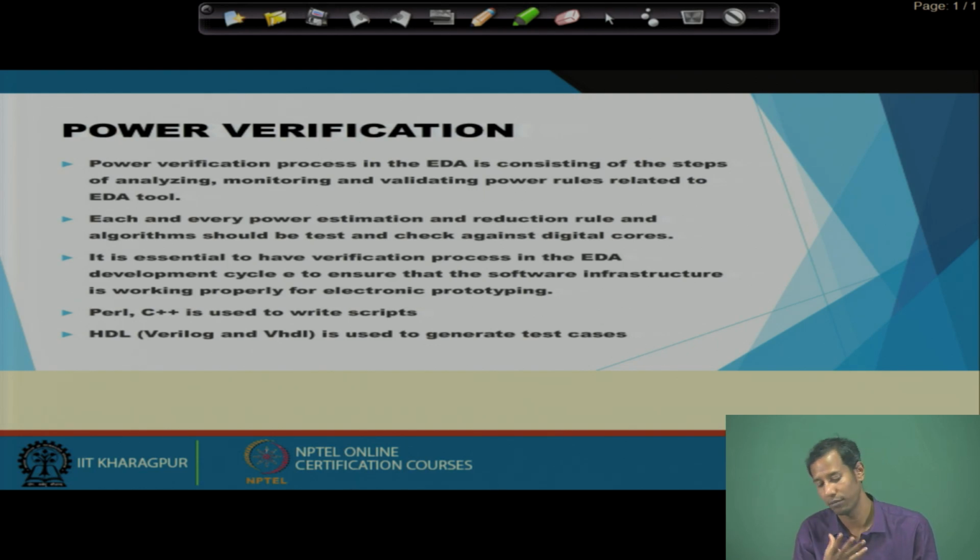So, all the switching activity information I store somewhere, and then if I give that switching activity to the tool, only then can it calculate, based on these particular simulations, that is, based on these particular test vectors, that this is the activity and this is the power report of dynamic power consumption, leakage power consumption, switching power consumption, or glitch power consumption, if there is a glitch.